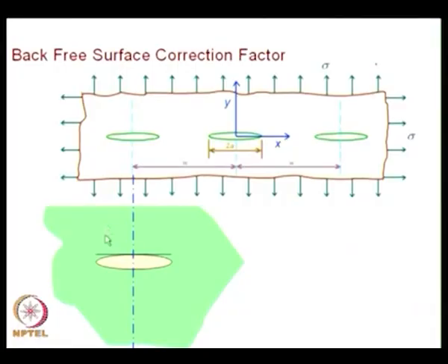See, the edge becomes free, there is no constraint that this slope has to remain horizontal. So, in essence, the crack will open up further, that is what is shown here. The slope need not remain horizontal and the crack will open up. So, for the crack to open up, you need to apply more stress.